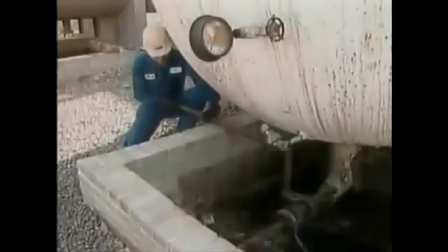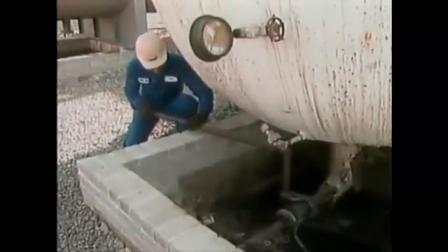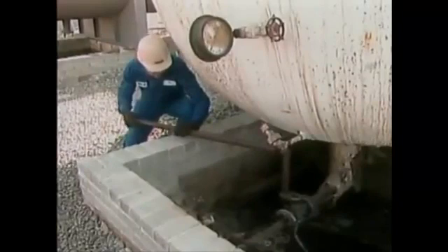A problem that may occur in gas systems is freeze-ups in the fuel lines. In cold weather, condensation in the fuel can freeze and create problems for the operator. A knockout drum can remove most of the condensation, but a small amount may remain in the fuel that's sent to the furnace. In cold weather, even a small amount can cause a freeze-up. If you do have freeze-ups, you may find them in low points in the fuel system, where moisture can collect and freeze.